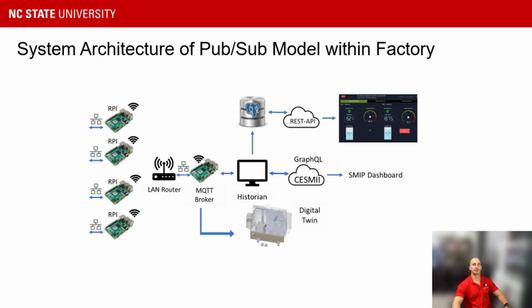Devices that might be part of a production cell can individually communicate with the broker on specific topics or collectively communicate to the MQTT broker via a production cell specific topic channel. The unified namespace architecture ensures that machine assets do not need to communicate with higher order information systems through specified controlled layers. Rather, a unified namespace is established that allows decentralized machine-to-machine or machine-to-cloud communication, without the need of centralized nodes that force communication between various levels.